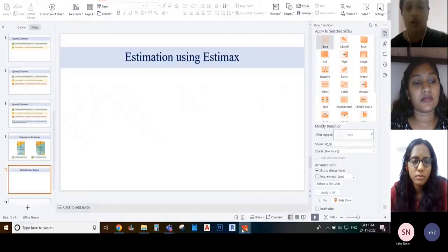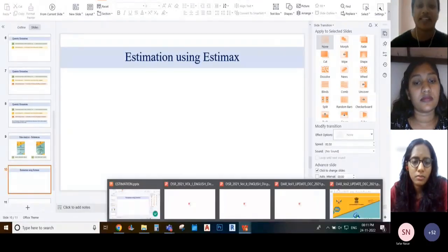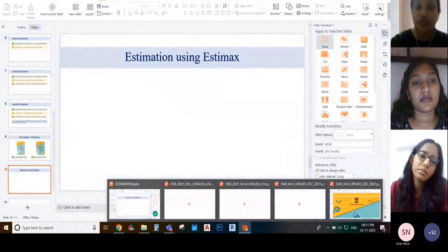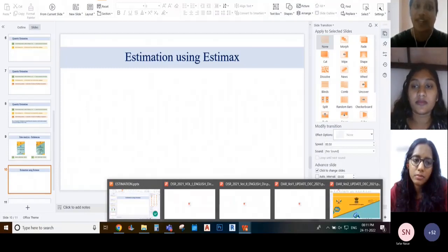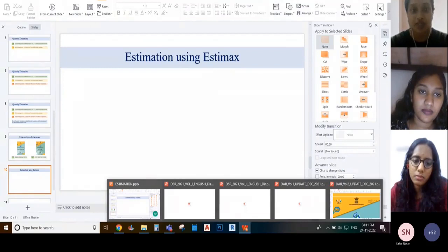Okay, now I'll open one. Firstly, I'll say which is a document you have to rely on for the rate of materials. Like, how will you know what is the rate of one brick, or the rate of one bag of cement? You can either Google it, but mostly you might get misleading values. So better you can go for DSR, or you can go for reliable market sources like Indiamart is one reliable source, but there too you have to make sure you are selecting the right material and right vendor in order to get the right rate.